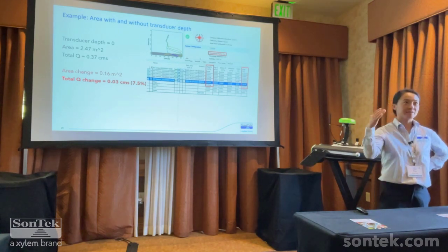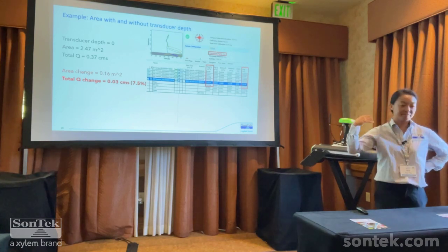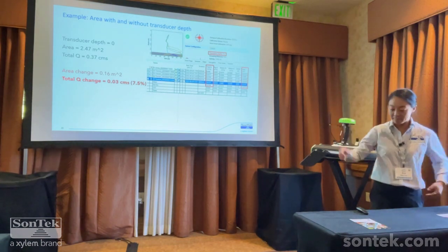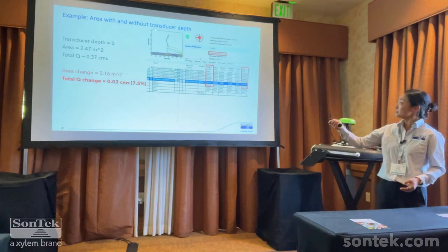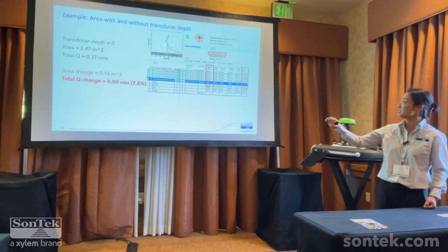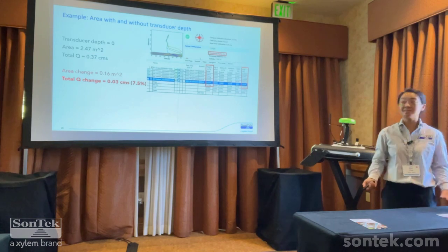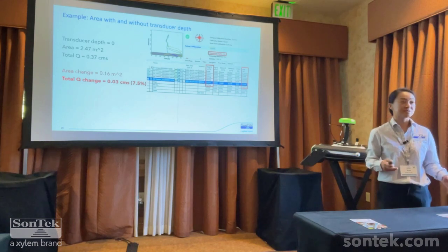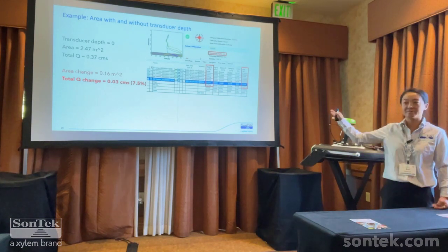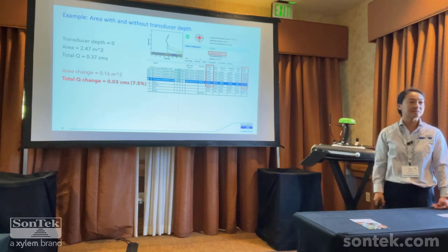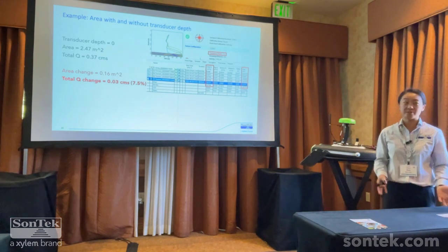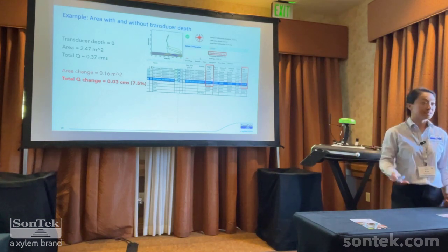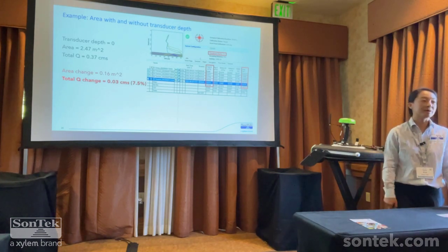If you do have stuff that's in the water, suspended, that's coming in the way of your actual measurements, you should be able to see that pop up. We have this profile plot here, and you'll be able to see these big spikes if there is interference. You'll get a whole bunch of warnings. The software might actually kick out those measurements and just not use them because they're bad. So there's a lot of QC going on behind the works here. Generally speaking, you should be okay, but just be aware and look out for artifacts and data that don't look right, because there will probably be some of those.